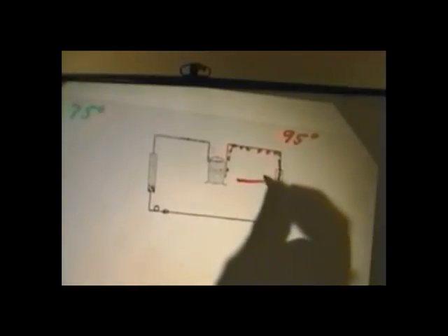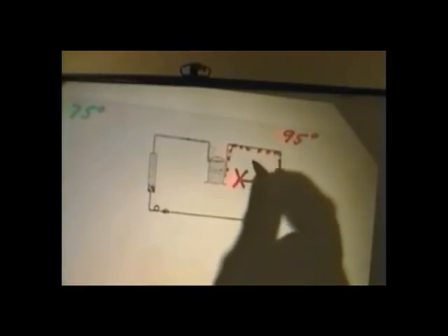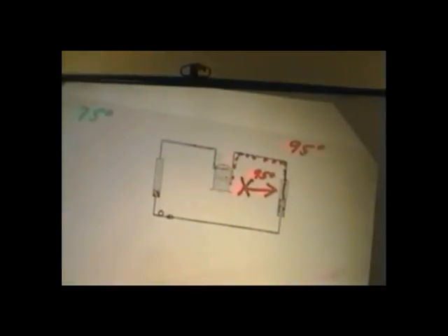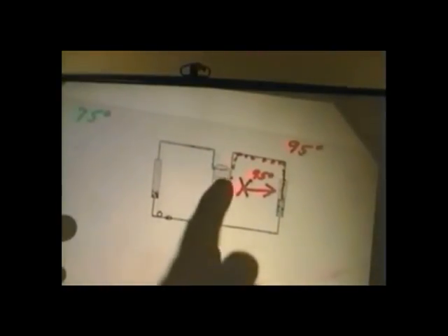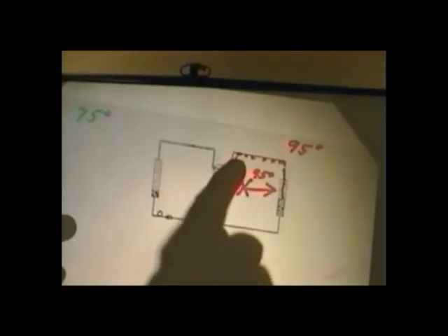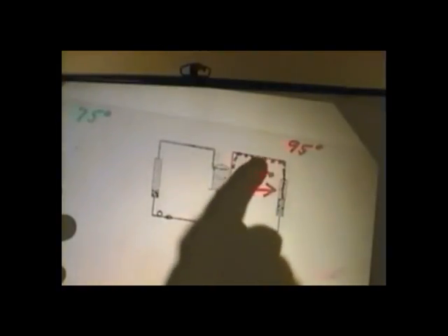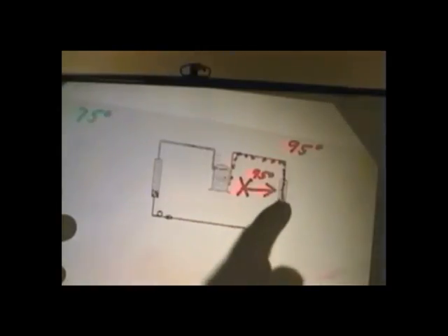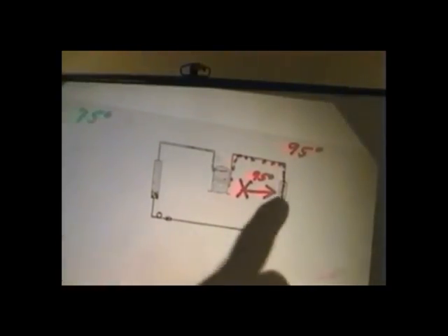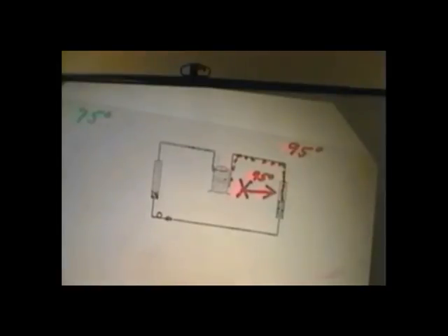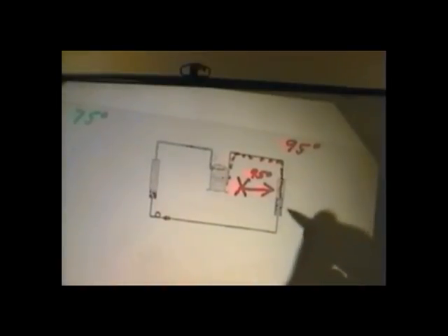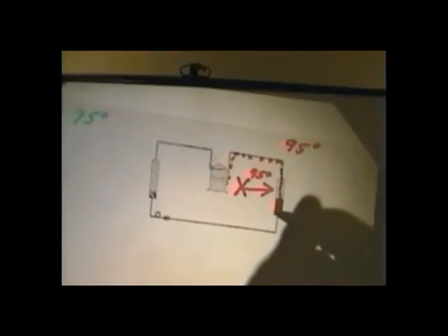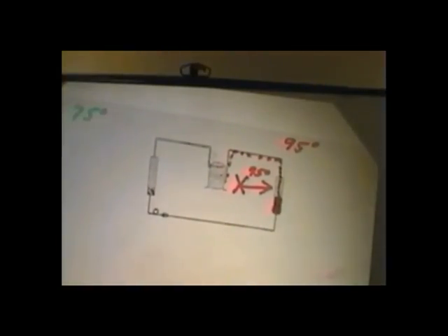So this is a normal system, and again, if it called for 50 ounces, that's exactly what we're putting into it. But under normal conditions, we would have a fan blowing 95-degree air through a very hot condenser. And the compressor is discharging that heat-laden vapor into the discharge line, into the top of the condenser. The top of the condenser with the vapor is much hotter than the 95-degree air. So the vapor gives up the BTUs to the cooler 95 degrees and condenses into a liquid. That's the change of state temperature.